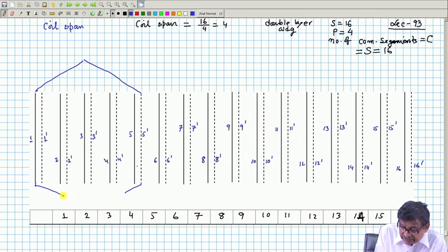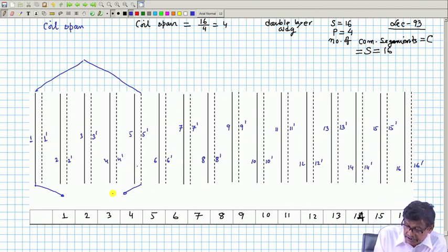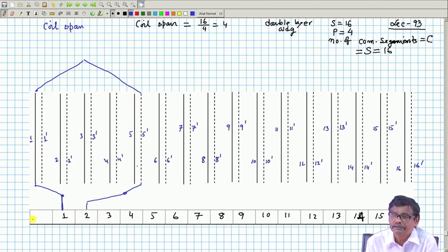Now, the question is, these are the two terminals of this coil. Where should I terminate? Here on the commutator segments. In case of lap winding, the coil side 1 you terminate on 1, and its return finish of this coil, that is 5 dashed, you terminate suppose on 2. Got the point? This is how the coil sides are terminated.